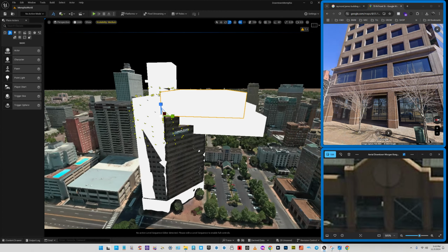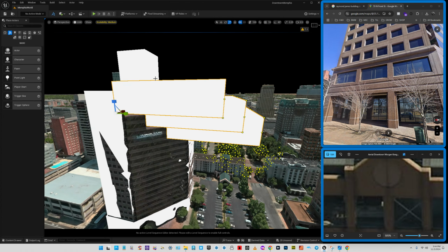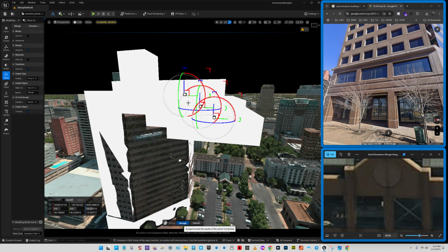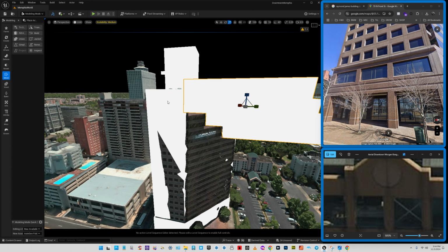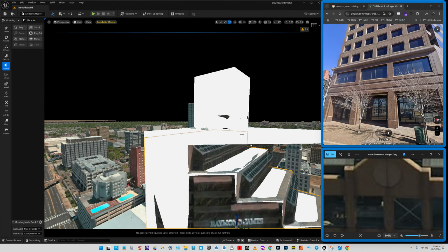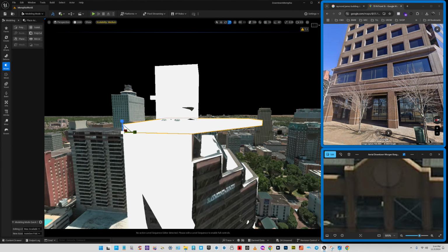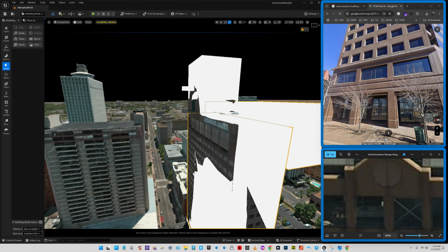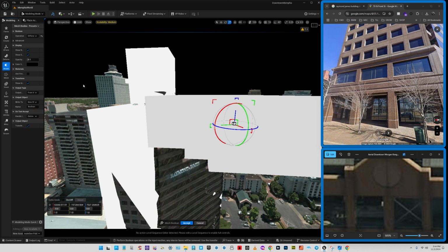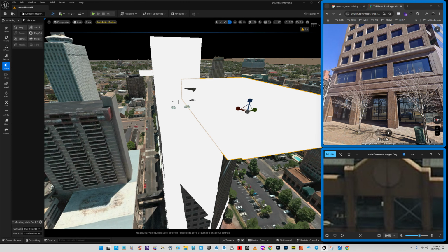And what I can do actually is join these three rectangles together using modeling tools, mesh union, except, and then I can do a Boolean under model, Boolean, except. All right, cool. But I need to go and undo that real quick and duplicate this Boolean. Let's do a Boolean on the building again, and then do a Boolean also on that little rooftop piece.